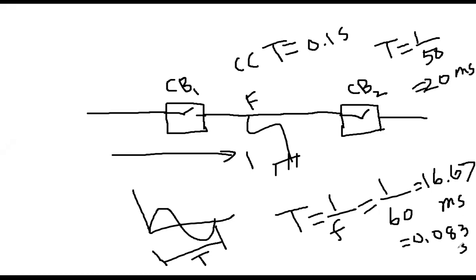What is that duration? From the initiation of the fault until the opening of the breaker. The breaker depends on the protective relay and the triggering coil, so it needs some time. That time is maximum 5 cycles, not more than 5 cycles, all over the world. Within that time frame, this circuit breaker must open to disconnect the faulty part. That time is called the critical clearing time.